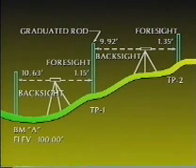The distance from the rod to the new setup point, the backside distance, should equal the distance to the next point ahead where the rod will be placed, that is, the next foresight turning point.